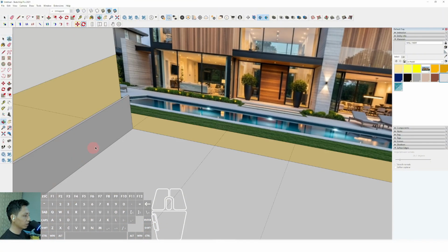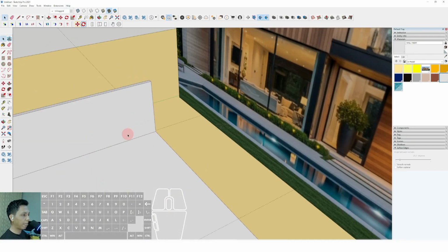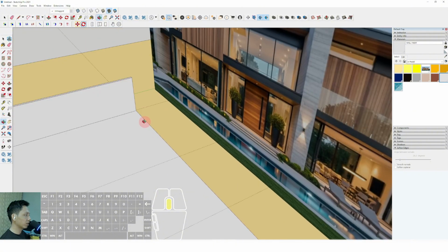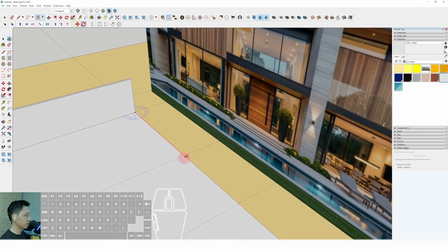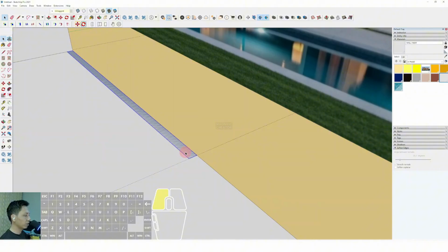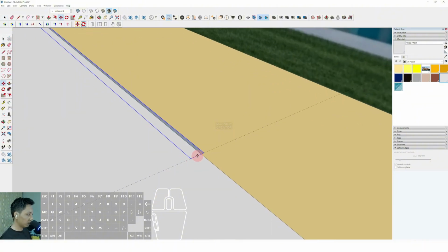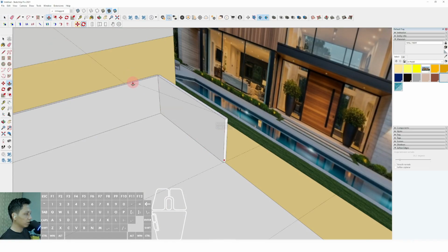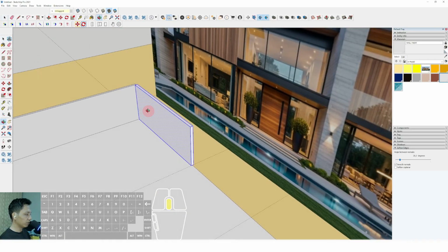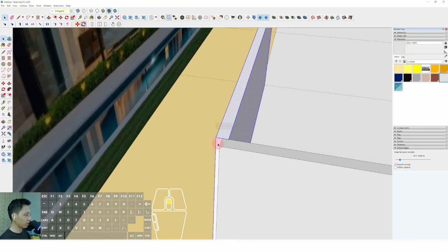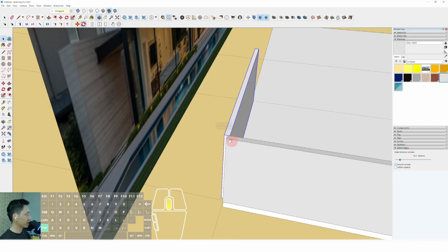You can use the wall again in here. We can use the rectangle and click from this position until this position. Okay. We can type 150 millimeter, enter, and we can move it to the middle. Okay. We can move it to the middle. Okay, please follow this step by step, because I will give you a dimension so you can try it by yourself on your devices. Okay.